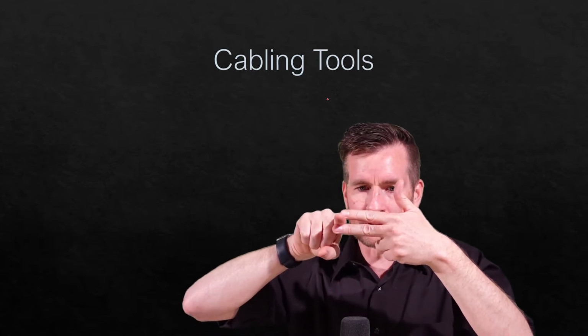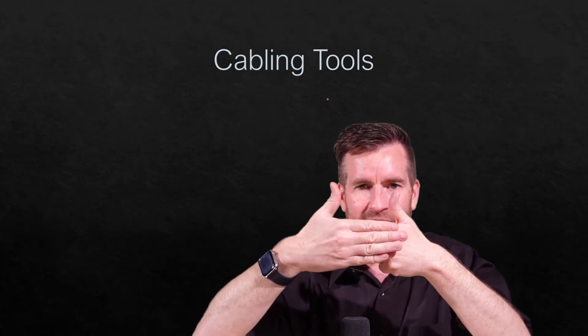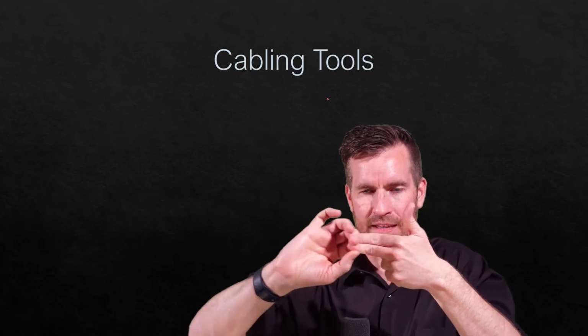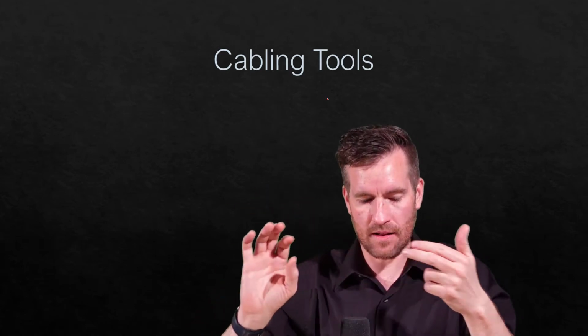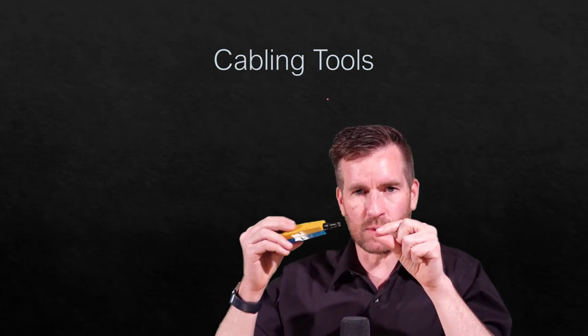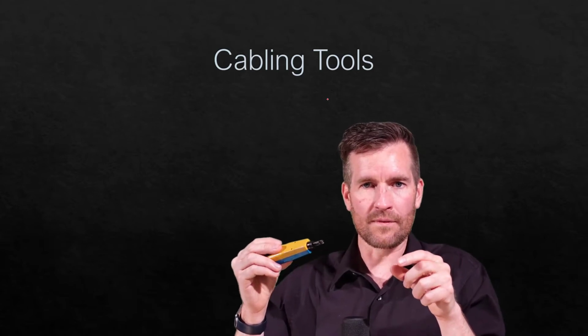And so this tool just pushes it down, and there's a little snip on it as well that shears that end off and pinches that end off, and so that way you don't have the extra ends to it. It makes it look sharp. And so you would use this like on the keystone jacks when you're creating the jacks, then you'd punch this down onto there.